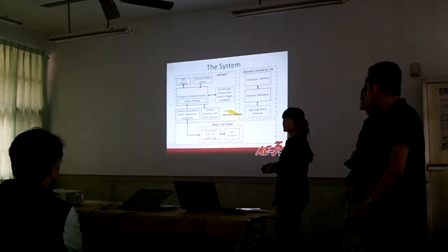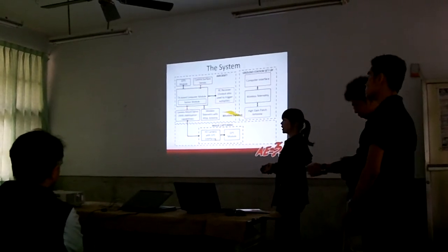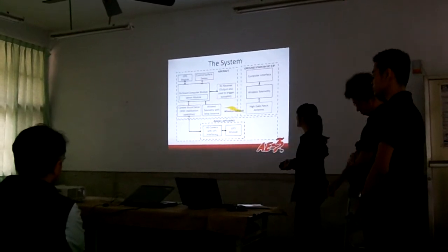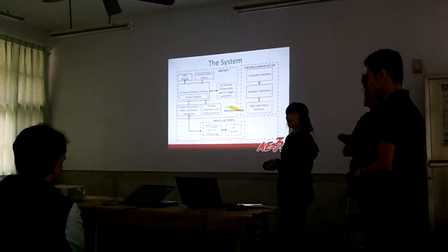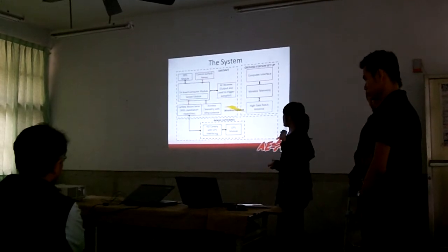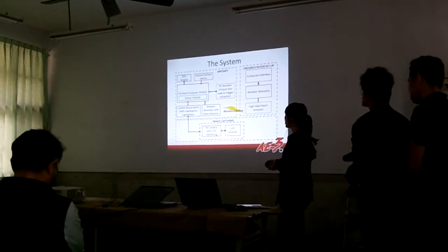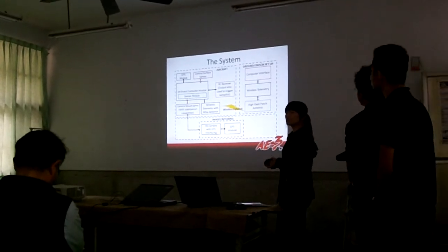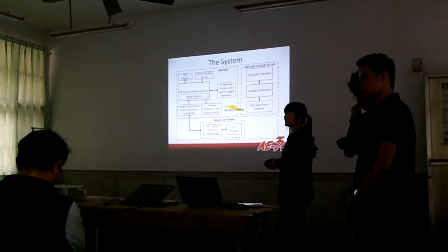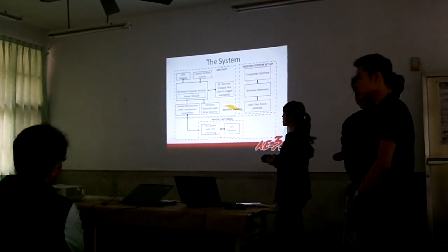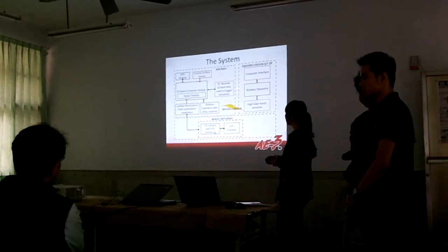Secondly is the ground station setup. Mainly these components are devices that we use at our ground station. So it includes our computer interface, wireless telemetry, as well as the high gain patch antenna, which serve to extend the range for our wireless data link. And image capturing is for the purpose of capturing image and to locate the GPS coordinates of the target. So we have the HD camera as well as the GPS module.